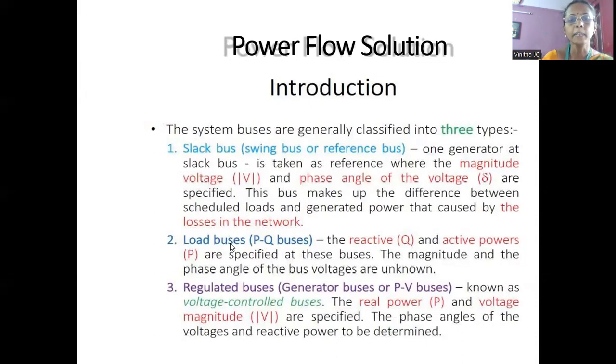The second type is called the load bus, otherwise called the PQ bus. From the name itself, the quantities P and Q are specified for the load bus. After solving the load flow equations, the magnitude and phase angle of the voltage are calculated.